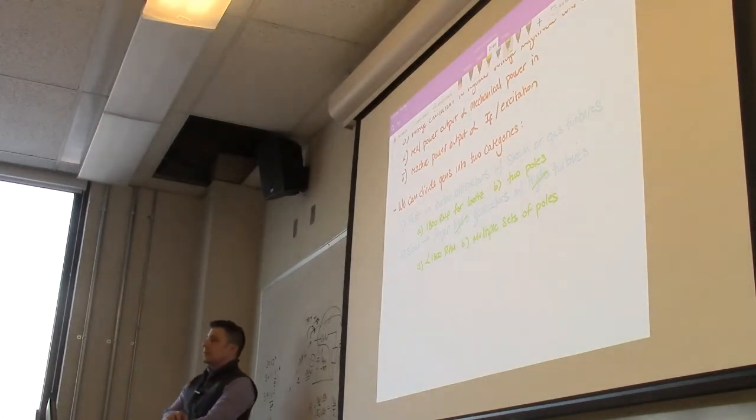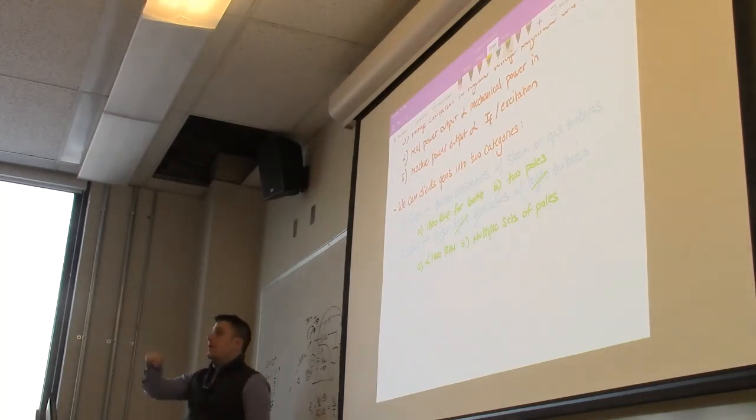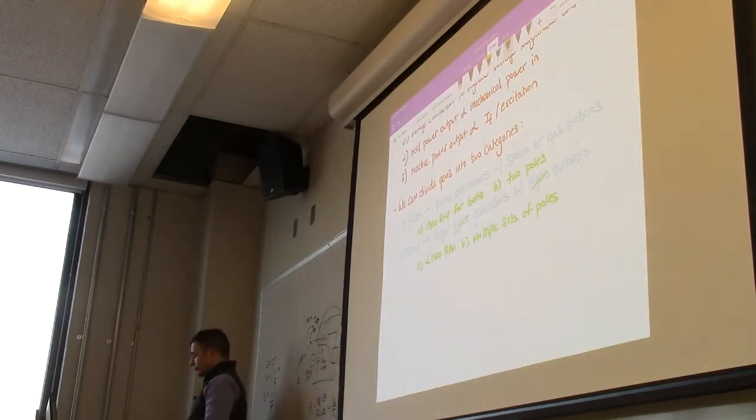Is there a significance to the RPM being 1800 as a set standard for dispatch generators? Well, we'll see in a second. If you take into account RPM and the number of poles, and then the rotational rate, that'll give you essentially 60 hertz. That's the value that lines up with 60 hertz.